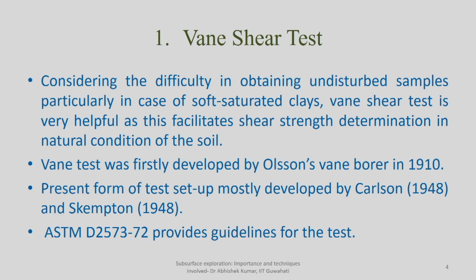So for the vane shear test, what we have observed is that it is particularly useful when the soil is very soft, particularly clays, and fully saturated. For such fully saturated soft clays, particularly if they are available at deeper depth, it is very difficult to collect an undisturbed sample. Whatever way you take to collect the sample, first of all there will be partial to more shaking or disturbance in the soil. Secondly, because it is fully saturated, once you bring it out onto the surface there are always chances that there will be a change in moisture content in the soil.